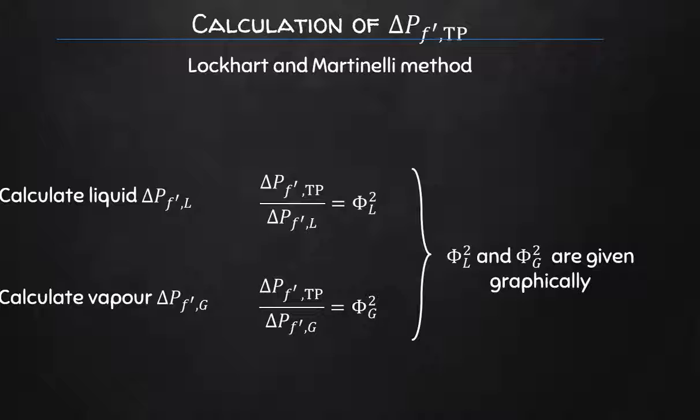So, how do we determine the pressure drops for these two-phase systems made up of liquid and gases? Well, one option is to make use of the Lockhart-Martinelli method, which was modified at a later stage. This is done by determining, firstly, the pressure drop associated to the liquid as if the liquid was not a two-phase flow, so if it was the sole liquid inside the pipeline.